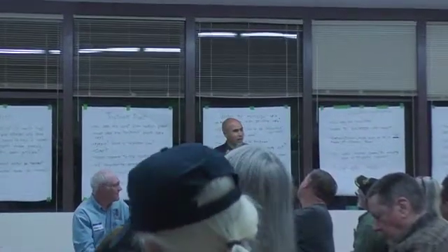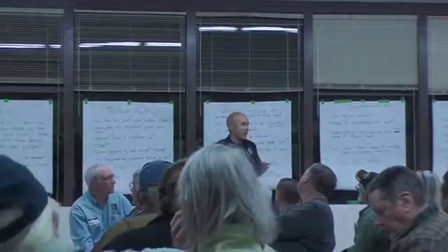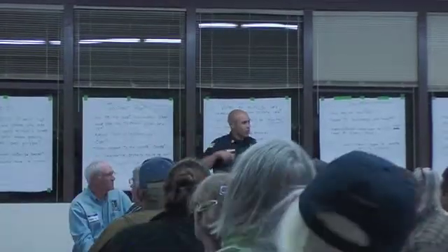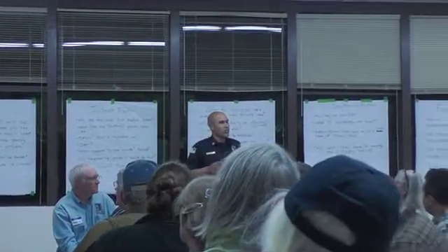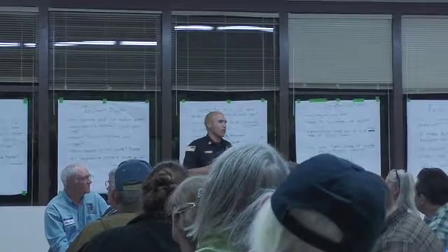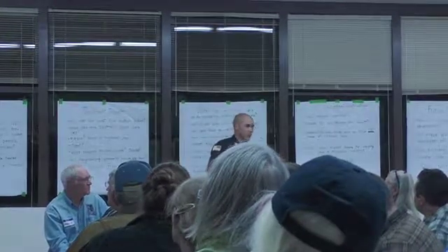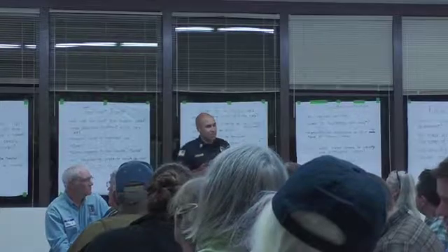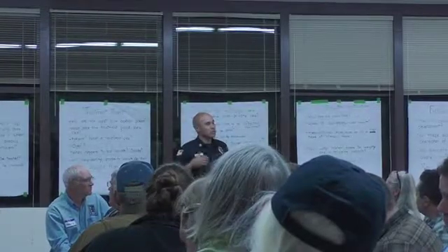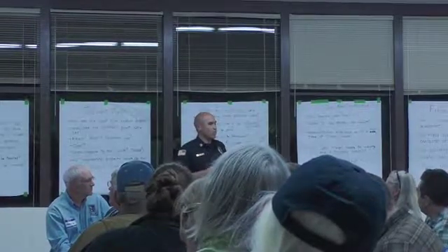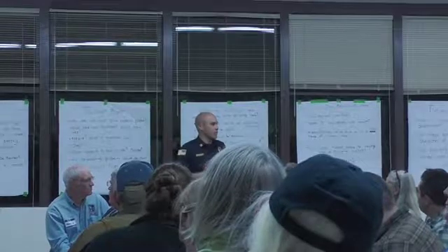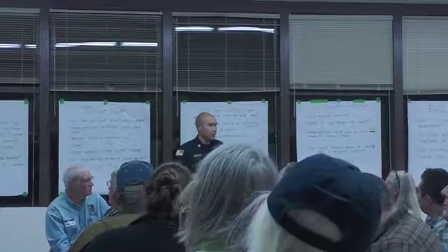I was just there today at the elementary school, and this is simply looking at the fire aspect only, not looking at all these things you guys are talking about. So just bringing the fire aspect to the table. I was there today doing my annual inspection, and when I turned on their fire hydrants, they were producing less water than an actual fire hose needed to put out the fire. If we had a fire at the school today, we would not be able to deliver enough water to keep that school from burning down if it was in a fully engaged, fully involved state.